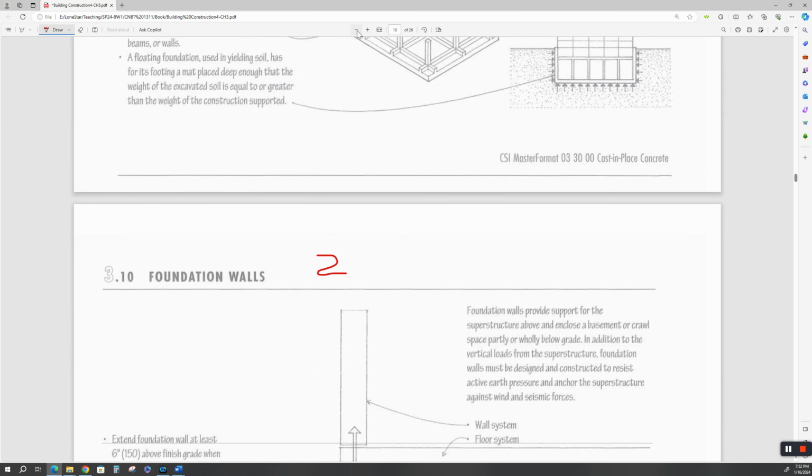I would not recommend to my architect to design it like this. This would be a monolithic slab. If we needed big spread footings down here, that'd be one thing, but then I'd have a construction joint in this wall with a water stop, be it an elastomeric water stop or whatever, and then I'd have a cast in place slab. Now, this shows a pre-molded filler or sealant at the expansion joint, so they're looking to control some expansion in this slab.